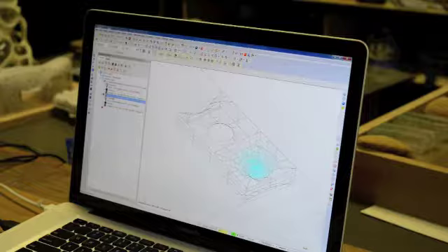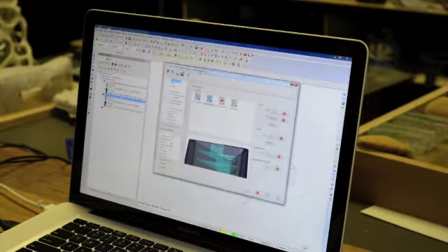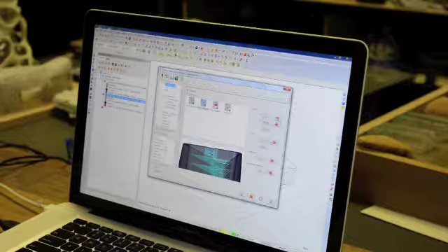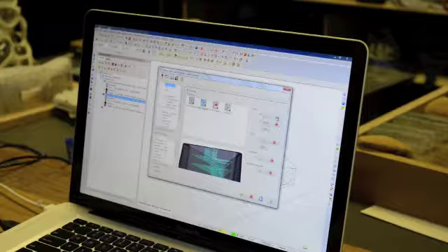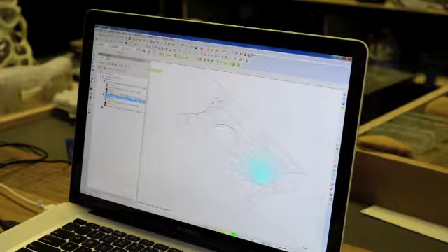So when you copy it, open your parameters folder again, and this time, because you made the copy and we're setting up a new set of drive surfaces, you click on this, which eliminates the existing drive surfaces associated with this particular folder. So we want to do that. Same thing with the containment, and you can also do it with the start point. So our new drive surfaces are over here.